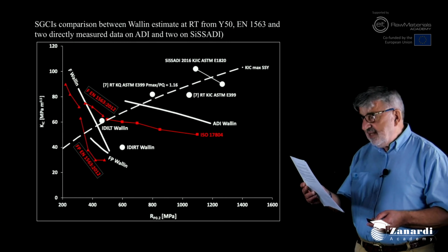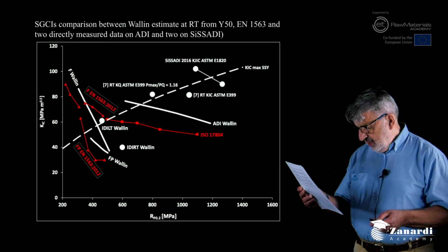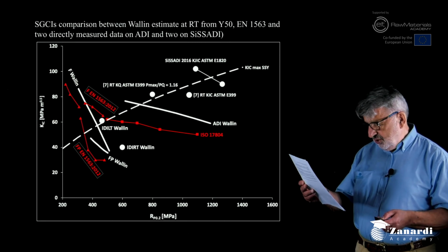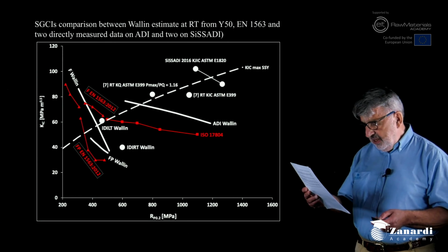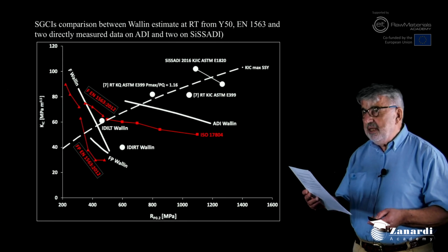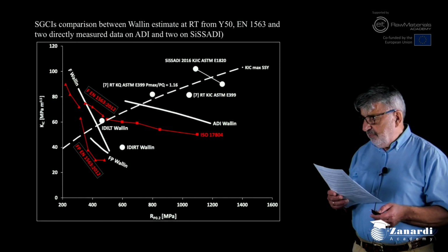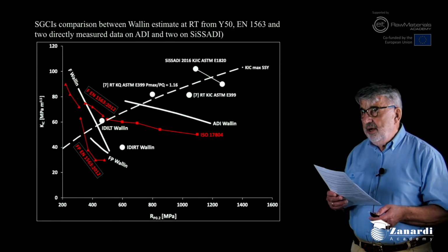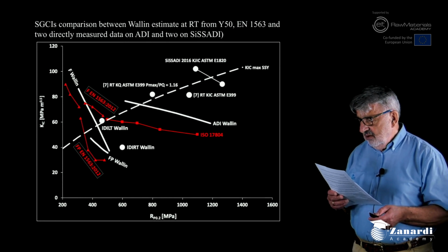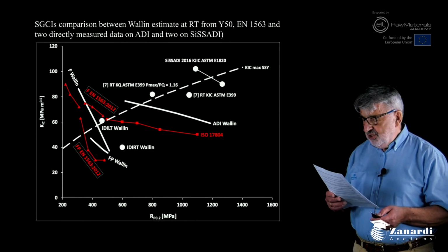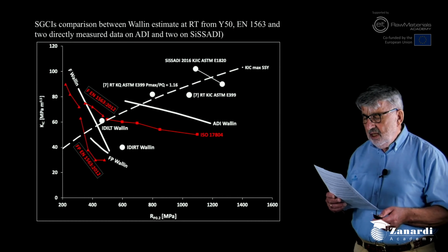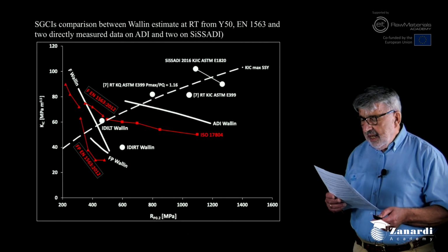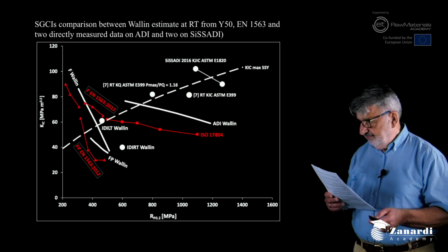ADI is low sensitive to strain rate. Then directly measured data and conversion from Charpy V-notch can be compared. Ferritic pearlitic and low normal silicon ferritic grades show the same trend from the two data sources, being, again, EN more conservative.